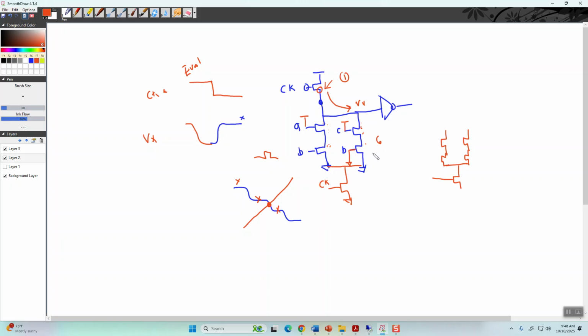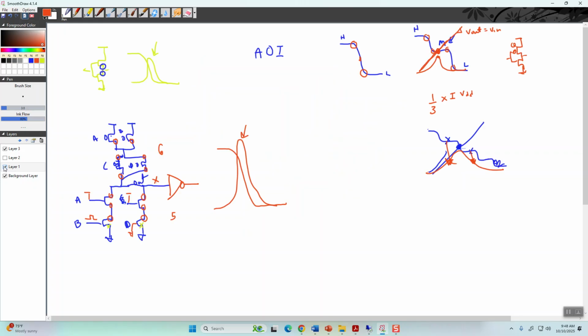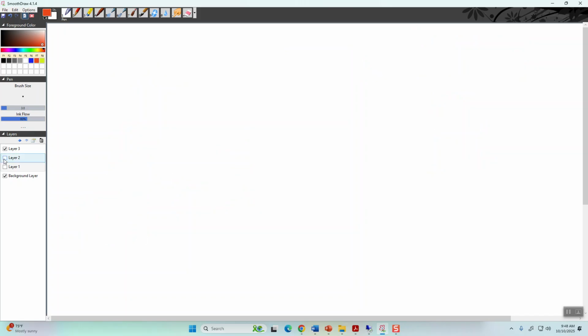Not quite sure why I said 5 the other time. Anyway, but we only have one. And the thing is if we go back here, something I failed to mention, is that to make the rise and the fall times equal, these PMOS, on average, have to be twice the width, which then they have twice that drain capacitance to discharge and charge. Okay.